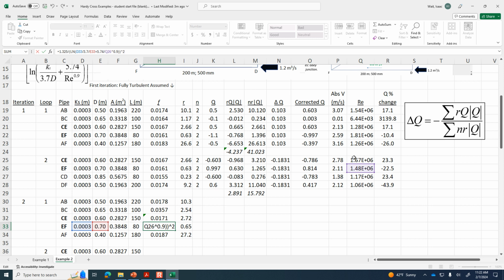So I've improved my F value guesses slightly by making that adjustment. It still would eventually converge if I didn't make that adjustment. That's not a fatal mistake. It's just an improvement. There are certain things that have to be perfect. This is one of the few that does: the F values just converge faster if you use the most recent Reynolds number.